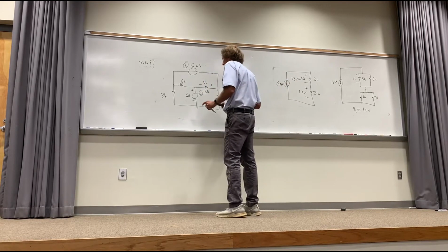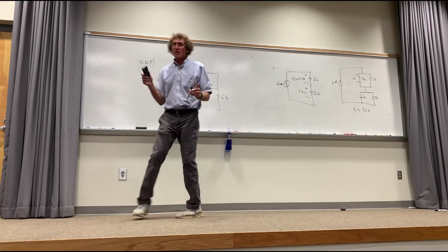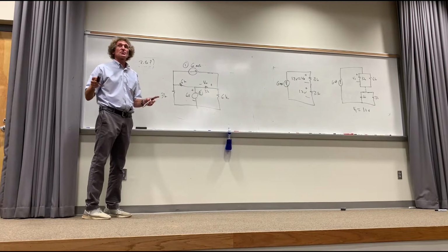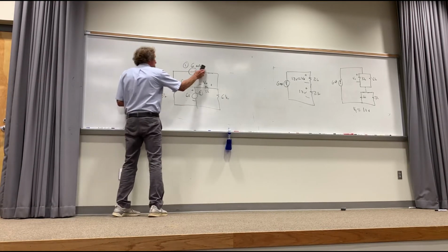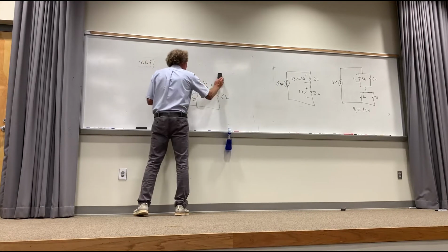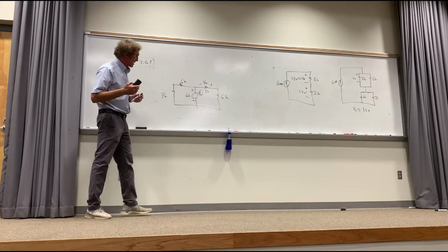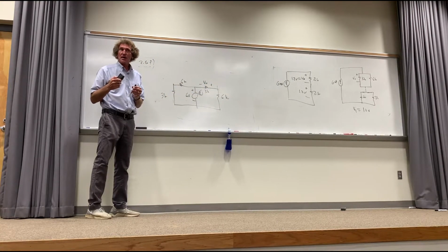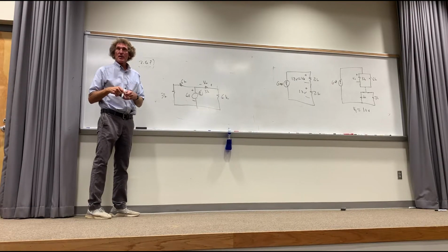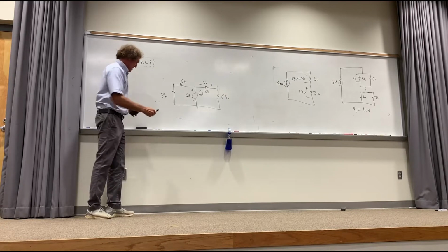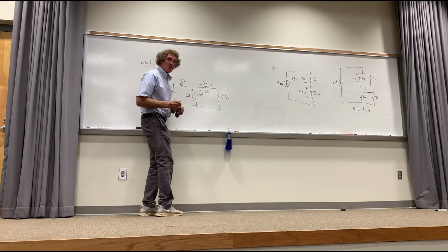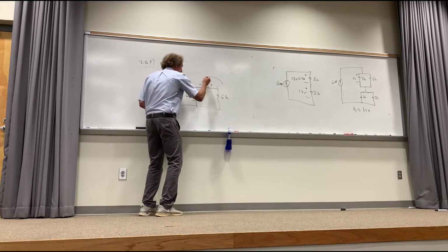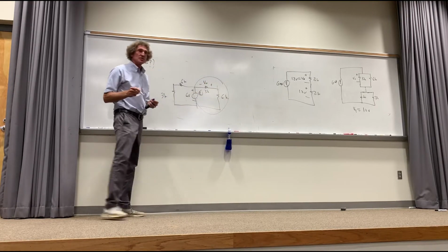That's our first voltage. Now for this one, we're going to turn off the first source. It's a current source, so it becomes an open circuit. Just erase it. Get it out of there. It does no good. Now this is my source. All right, this is my circuit. Can you all see that? Now I want you to notice this. Please just listen to me. Can you all see that's a voltage source, right? That voltage is across those 2 resistors. Do you all see that?